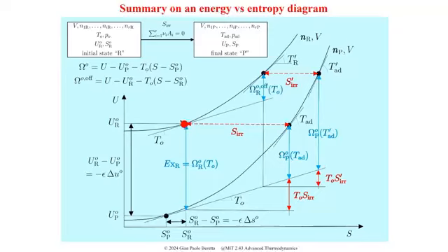When I do the flame, the adiabatic combustion, I end up with this state here, and its availability, its available energy. As you remember the construction, you have to go down here geometrically until you reach the line that has the slope of the temperature of the reservoir. So this is the blue. This is the available energy.